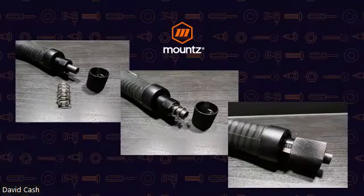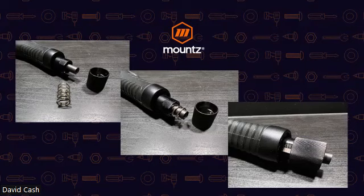And so if we take a look at this example of a torque screwdriver, if we remove the cone of the tool there, you can see this is where that spring lives. And as we adjust the amount of pressure that is on the spring itself, that is going to be what is generating our torque value. And so with the reference marks that are located on the tool, those again are just reference marks.